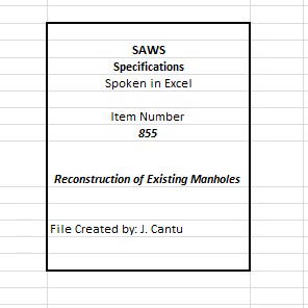Manholes shall be tested after construction/installation and backfilling with all connections, existing and/or proposed, in place. 1. Drop connections and gas sealing connections shall be installed prior to testing. 2. The lines entering the manhole shall be temporarily plugged with the plugs braced to prevent them from being drawn into the manhole. 3. The plugs shall be installed in the lines beyond drop connections, gas sealing connections, etc.